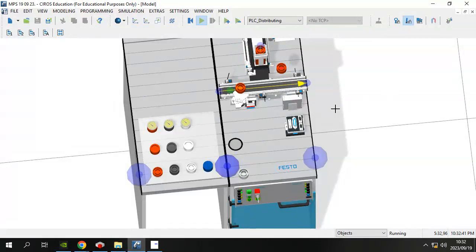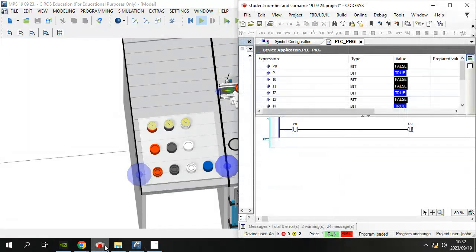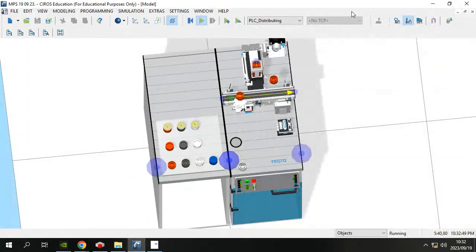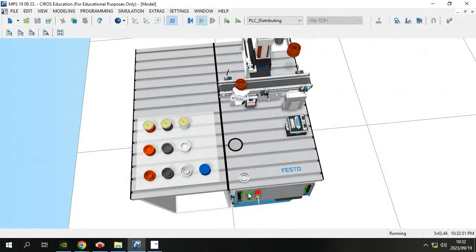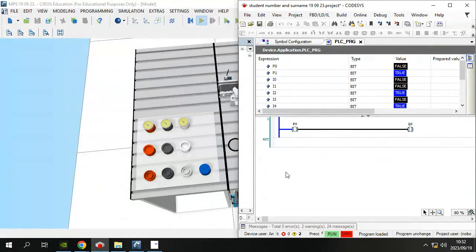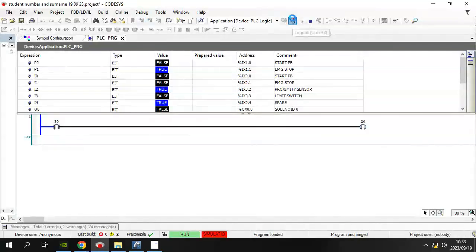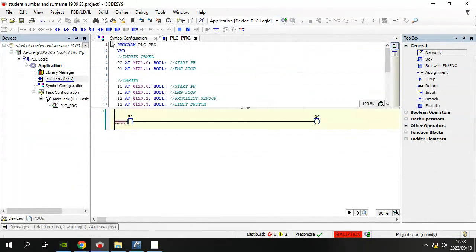Okay, so now let me just draw a small one, just to make it go and stop. So now, the shortcuts that I discouraged, remember, I press here, it just moves slightly. But on the fluid sim, when you did this, you were able to get it to extend, isn't it? In this case, it doesn't run forever. It requires you to give it a latching circuit, for instance. So those shortcuts really need to be informed shortcuts.